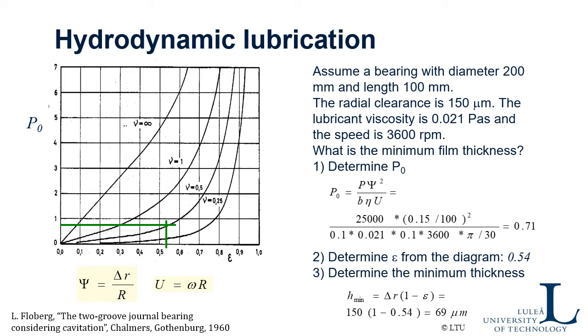must have it. It's a turbine that will operate for years, and we mustn't have a mixed lubrication in such an application. But I just wanted to show that it's easy to compute or estimate the film thickness in a journal bearing like that.